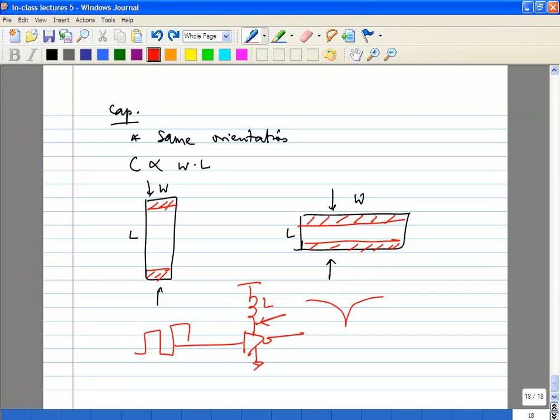So if you look at the voltage here, you're going to see actually much worse than this. You're probably going to see something like this. It can drop very low depending on the current you are drawing. It won't be VDD anymore. For the course project, we're just assuming ideal VDDs. But in the real case, remember that from the circuit you're routing a long way to the pad. You have a bond wire which goes off chip. You're going to route on the PCB and go somewhere else.